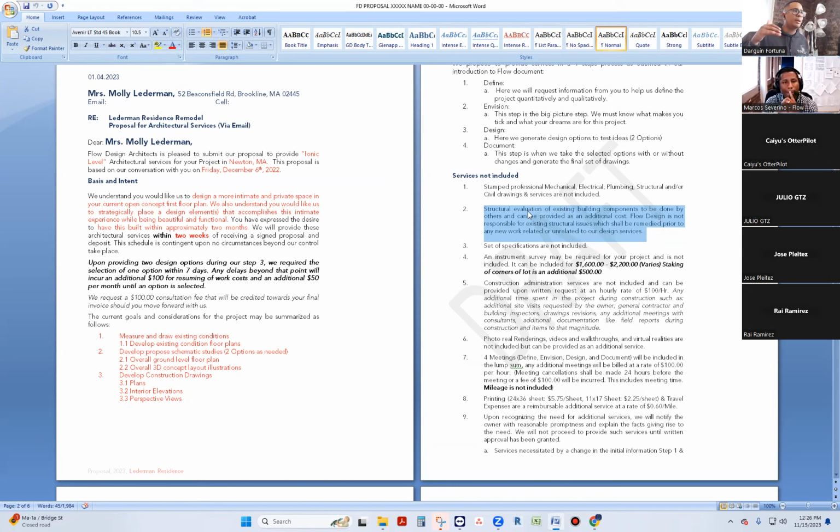So on the framing, let's make sure we ask: do we have a consultant involved or not? Generally say, look, we're not structural engineers. Whenever I say, well, this frame is like, we're not structural engineers. You can get your lumberyard to stamp it. You can get a third-party engineer, or we can hire one as an additional service. We shouldn't stamp. So yes, that's another thing.